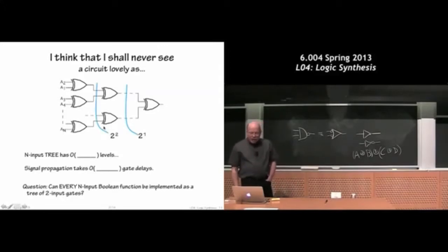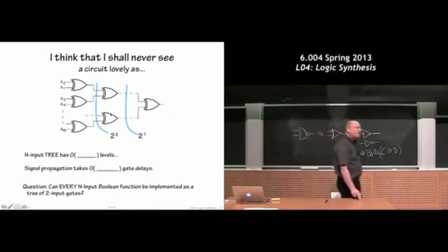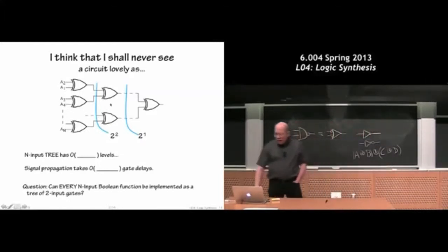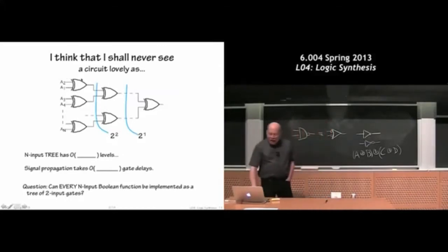And you can see what we're going to do is that for each layer of the tree, we're doubling the number of inputs that the circuit can handle. Because each time we add a layer to the tree, for every input at the previous end leaves of the tree, when I add a new layer, for each input, I'm basically doubling the number of inputs that I can accommodate at the next layer. So the number of inputs is growing exponentially as I make the tree deeper and deeper.